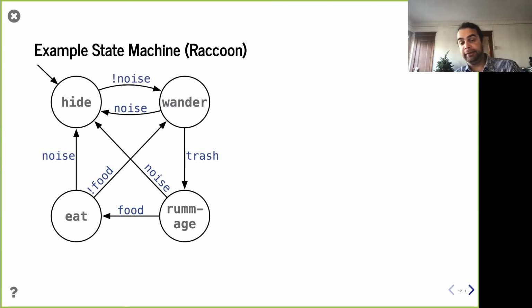Well, we're going to go ahead and make a state machine. So remember, finite state machines are a way of capturing how something moves between states. The way they work is you have a state you are in, represented by a circle, and that has certain actions or outputs associated with it. Then if you receive an input, that's one of these labels on an arrow, you go to the next state depending on whatever conditions are met.